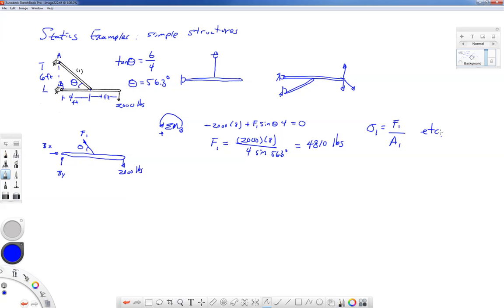Now here's where I see people mess up. Instead of drawing this free body diagram, they will draw a free body diagram that looks like this picture, where I have a pin reaction here, and then they'll draw in a pin reaction up here. And if that's point A, maybe this is AX and this is AY. While this is a free body diagram that is accurate,